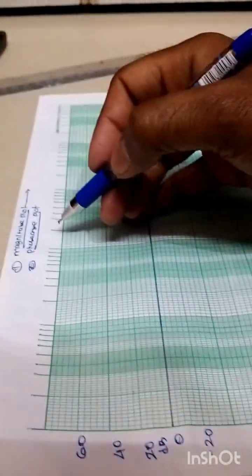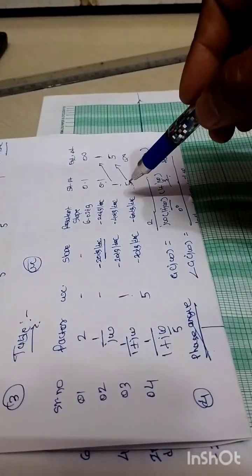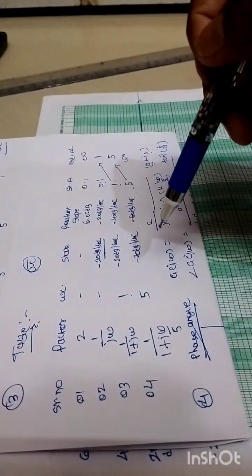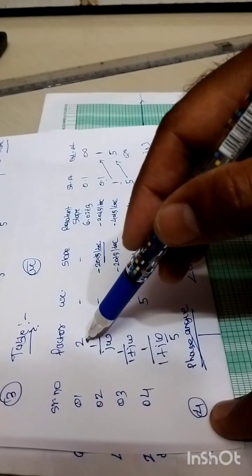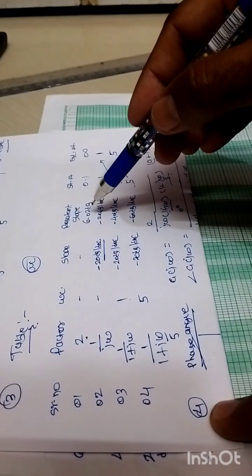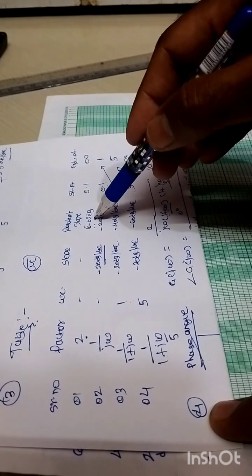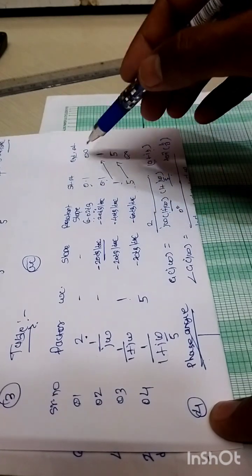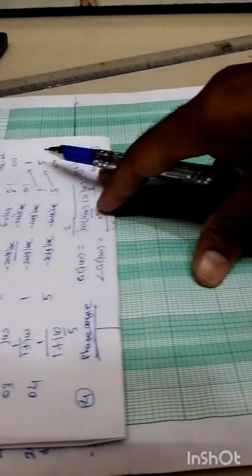Now in order to draw this magnitude plot, we need to consider the desired table, which was already tabulated in step number 3, right? This is the table for the magnitude plot. As you can see, for the first factor, at which desired decibel value do we need to plot it? At 6.02 dB, right? It starts from this point and ends at infinity. The starting point is how much here? 0.1.